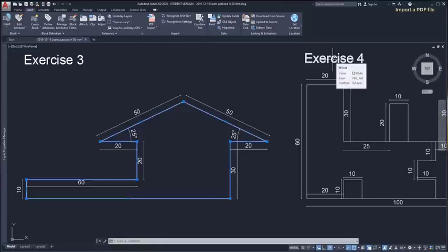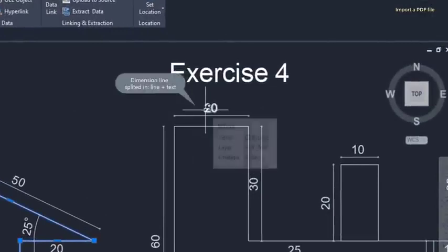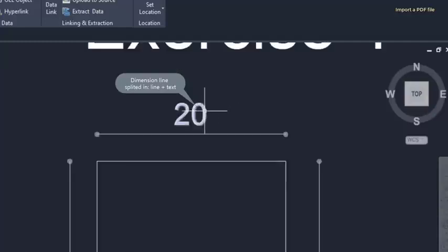If the text was not on a TrueType font, it would be split in very small lines and arcs, which wouldn't be so interesting. However, not everything is perfect. The dimension lines are not recognized, neither block references, which means I have to create them again. But in general, Insert PDF can be very useful. Just be aware, it's only available in the versions after AutoCAD 2017.